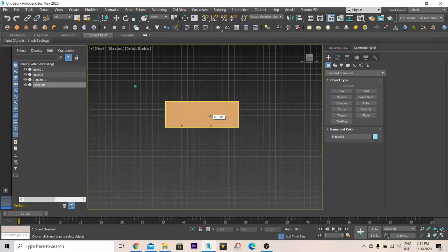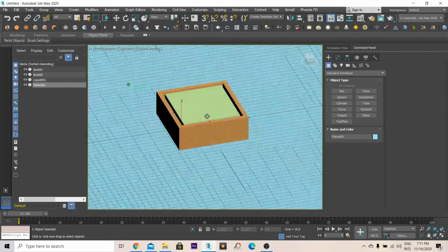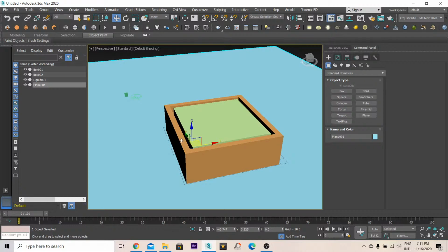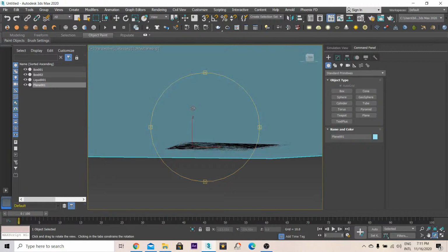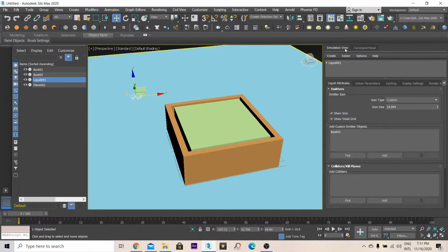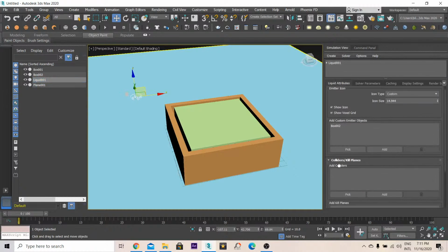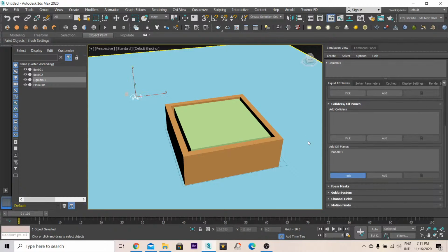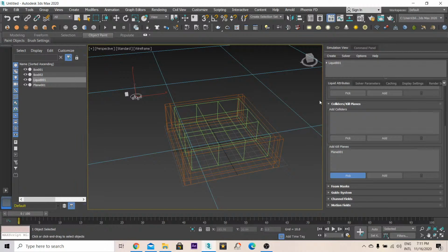If the liquid hits this plane, it will get deleted because we don't want it to simulate below this. So coming back to this, for that colliders are kill plane, so just pick kill plane as this plane, and now we can hide this.